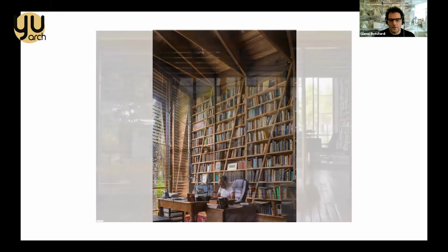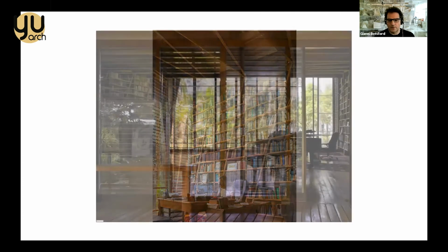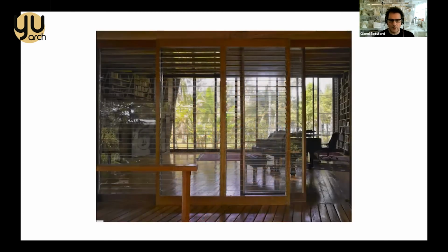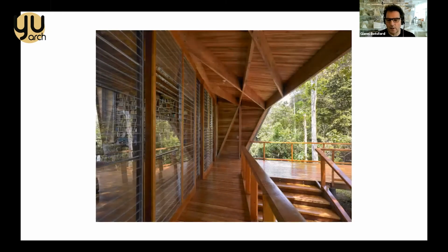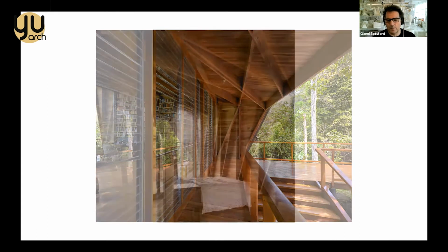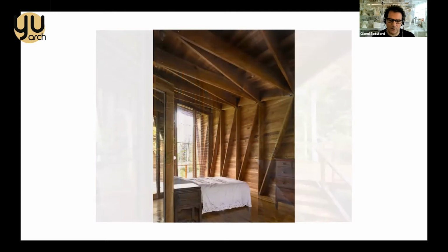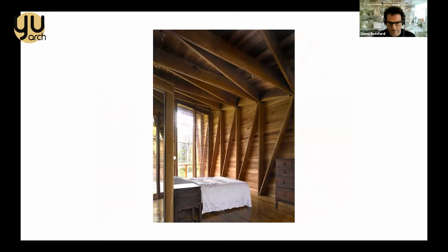There's a locally produced louvered glazed facade system that we use with sliding doors, so you can completely open the facade when you want to and let the breezes run through. So the whole building was naturally cooled and naturally controlled by the protection from the sun. And these large overhanging parts of the building, again, you could sit out, be protected, but it again shows how the glass is protected. And then to the rear was a bedroom wing that had quite a different atmosphere, using the same structural system, but facing the jungle with a calmer feeling to it.